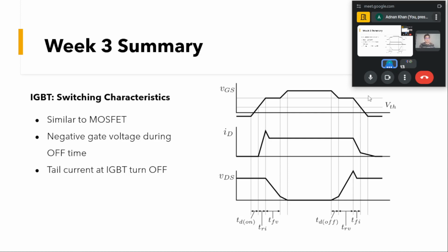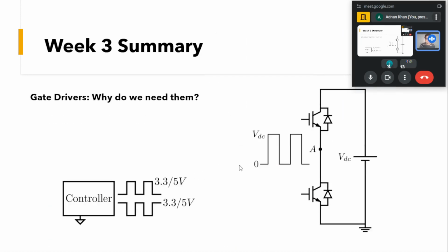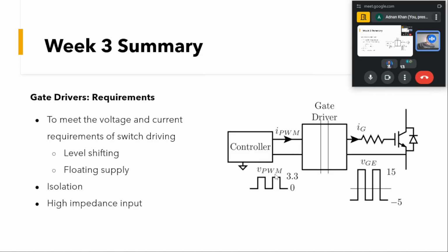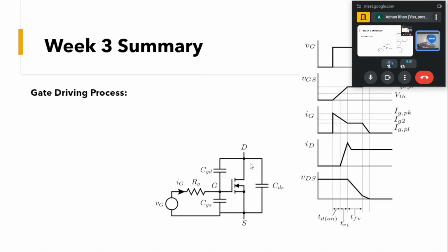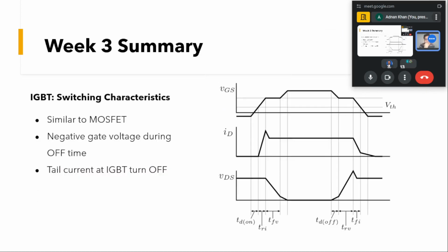Okay, what happens is, we'll come to the switching characteristics here, and when we see the gate drivers we'll see it in detail in the subsequent slides. When this voltage is applied, the device tries to go into conduction mode, and the current starts to flow through ID.